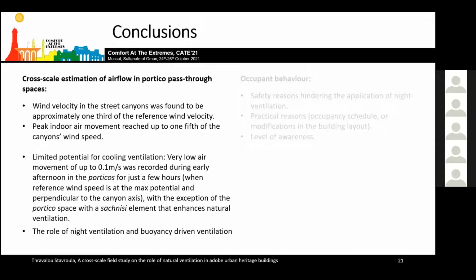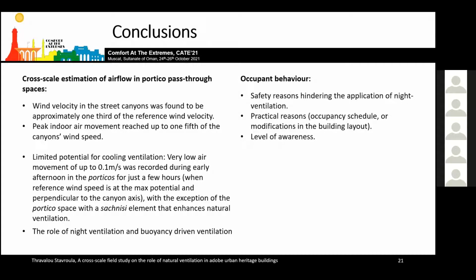Reflecting on the observed occupant behavior, several key points were raised. Firstly, safety is a major concern for occupants, hindering the application of night ventilation. Secondly, while vernacular dwellings provide the opportunity for buoyancy-driven ventilation, upper windows are difficult to access, thus they tend to remain closed. Regarding the level of awareness, in some cases, occupants seem to be aware of the way thermal mass works, maintaining greater ventilation rates at night and obtaining thermal comfort for most of the time.